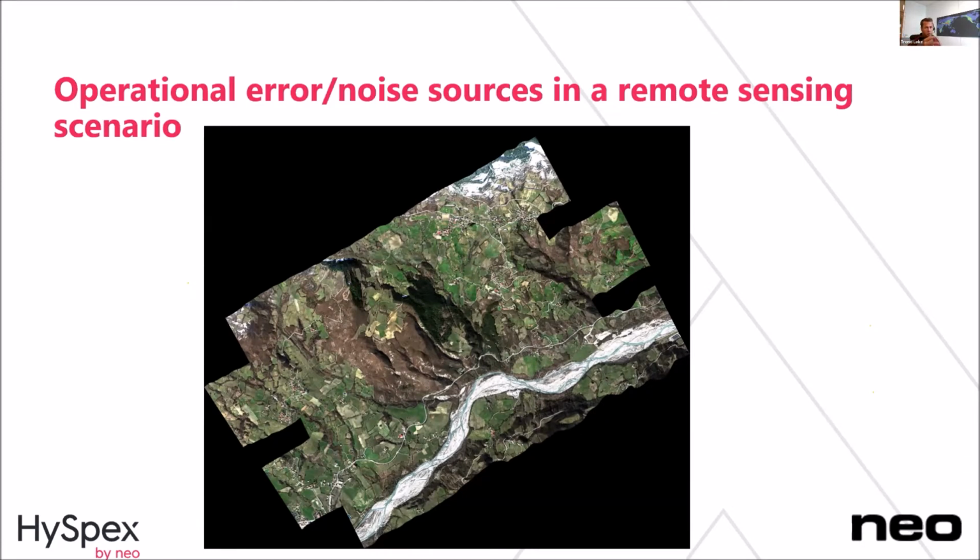But I'm actually working in the background here before this talk, processing the data for the session tomorrow, looking at Agnar's camera. It has been standing for 4 or 5 years, hard mounted to the floor in this passenger aircraft without damping. I see some slight striping in the image, which is usually caused by dust. We do all this in a flow bench when we mount everything together to make sure there's no dust. But if a dust particle hits the slit, you can get striping in the image.